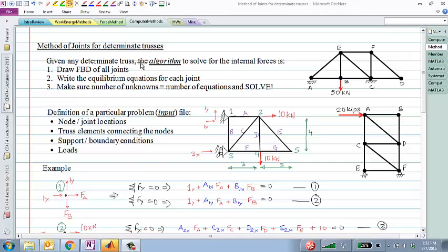The program, by the way, anybody tried to run the program that I posted on Blackboard? There is a MATLAB program on Blackboard that solves determinate trusses, which you can use now for solving indeterminate trusses, because essentially for solving indeterminate trusses, we break it down into a system of determinate truss and a redundant truss, and then superimpose them, right? So you can still use that program. I'll also give the program for the handout that I've just handed out, which is indeterminate trusses.